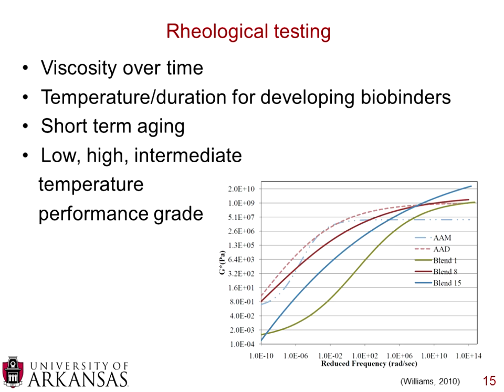So if you ever are looking at asphalt cement and you see AAM, AAD, any sort of sequence of 3 letters with a lot of A's in it, chances are you're looking at one of those original SuperPave binder asphalt cement samples. Because when they went through all this testing and developing of the equipment, they also pulled out a large amount of samples from this set of material, and they've just been storing it. So whenever any new material comes out or whenever some new technique comes out, they can actually compare it to the original binder. So that's what the AAM and the AAD are, kind of traditional asphalt cement types.